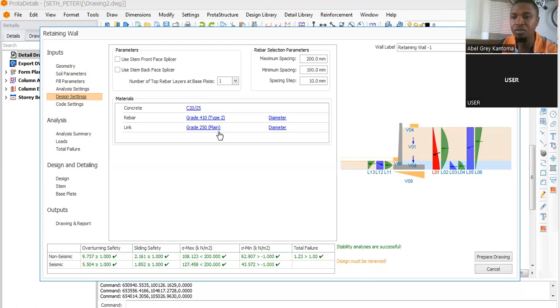The characteristic strength of your concrete is gotten from the lab. You have to run a test on your concrete in order for it to meet that strength. Okay, where you take your concrete cube to the lab, in your concrete lab, and then you run tests on them, and then in your casting on site, you must make sure that your concrete grade is up to that standard.